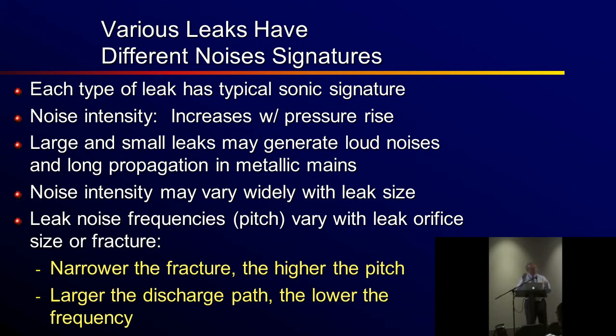So it's pressure, size of orifice, cavitation, all have an effect on the pitch of the noise that you'll hear. Narrower the fracture, the higher the pitch, the larger the discharge path, the lower the frequency, in my experience.